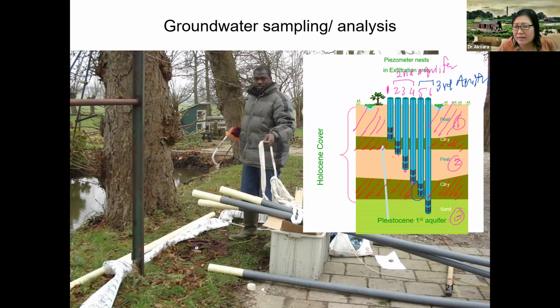I'm going to say that the reasons behind this probably consist of 2 reasons. First, they want to see whether you have a leaky aquifer system or not, so they take samples from the depth that seems to be the clay layers. If you can take some water from that clay layer, that means your clay is actually transmitting some water.